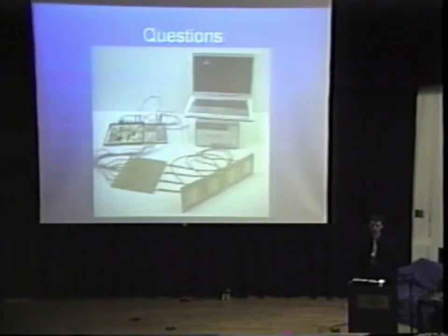Oh, okay. Phil wants me to mention working with surface mounts. For devices at 1.5 gigahertz, at very high frequencies, you have to use very, very small devices because the lengths of the traces and connectors all play a role in the performance of the system. For this one, I had to use very, very small components, like the resistors and the capacitors, and we had to get special tools, a special soldering iron, and a big magnifying glass. So it was sort of difficult to do the surface mount, but once you got the hang of it, it was all right. Any other questions?